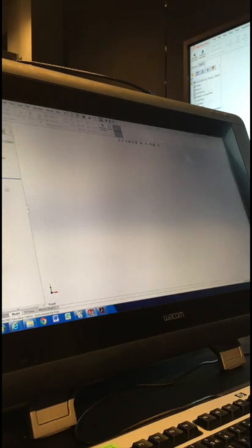On the left of the screen, this is your feature tree or property manager. This area will change depending on what you're currently doing, but by default it'll show you your feature tree. There are a couple of smaller tabs in this one. The very first one is the feature manager design tree. We've got property manager, configurations, dimension expert, and display manager. Again, we don't touch many of those. We will look at configurations in maybe week 3 or 4. Display is to do with rendering and appearances, and we'll look at that towards the end of semester. Most of the work will be left in the design tree though.